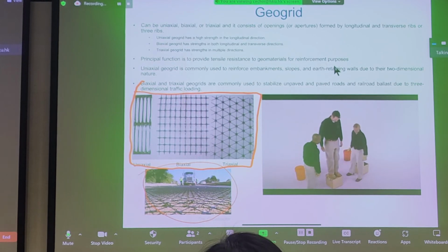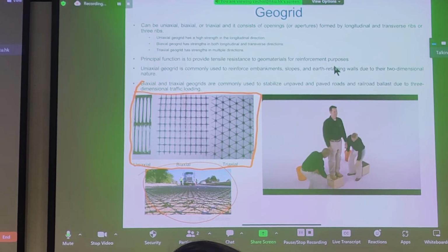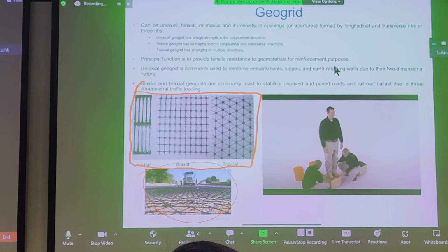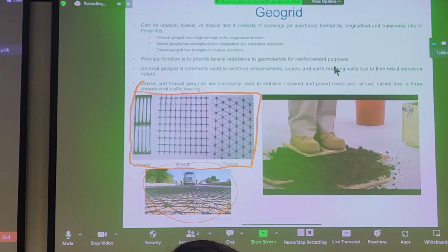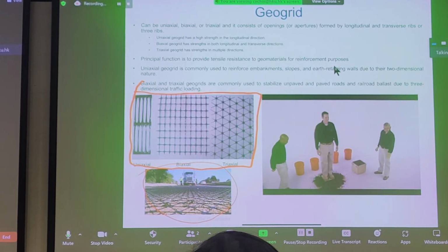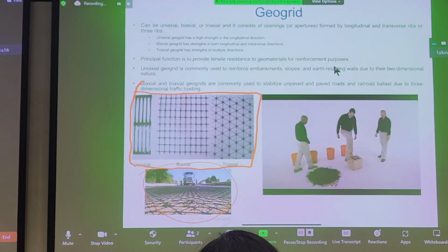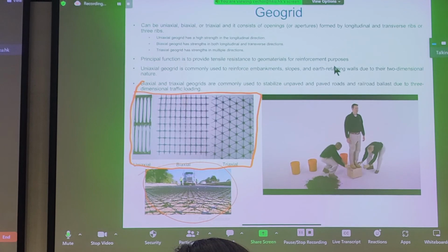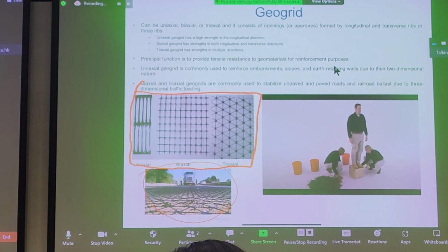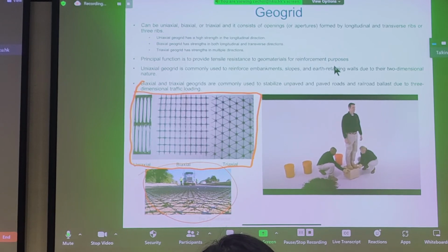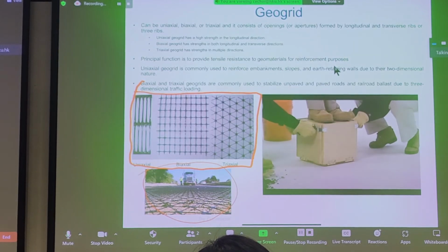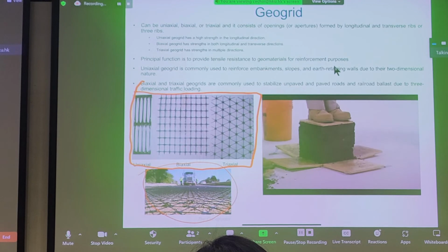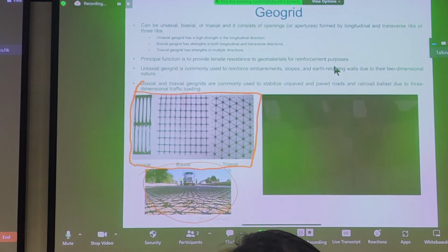For this first box, there's no geogrid, there's no reinforcement, and these two assistants will pull it, and there's no tensile resistance, less shear resistance, right? And it just flaps. The second one, on the other hand, has 3 sheets of geogrid, and I just want to showcase that geogrid is usually used to enhance shear resistance of soil by enhancing the tensile resisting component.